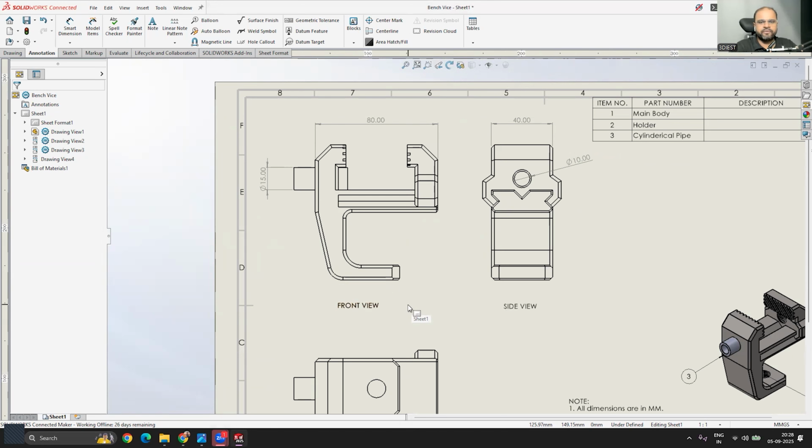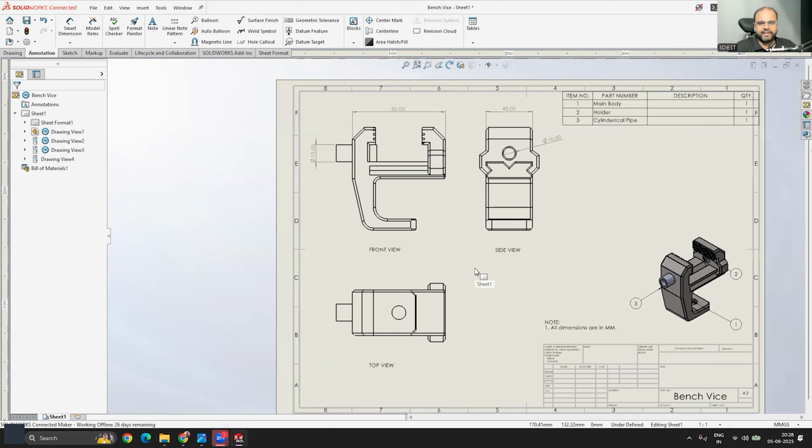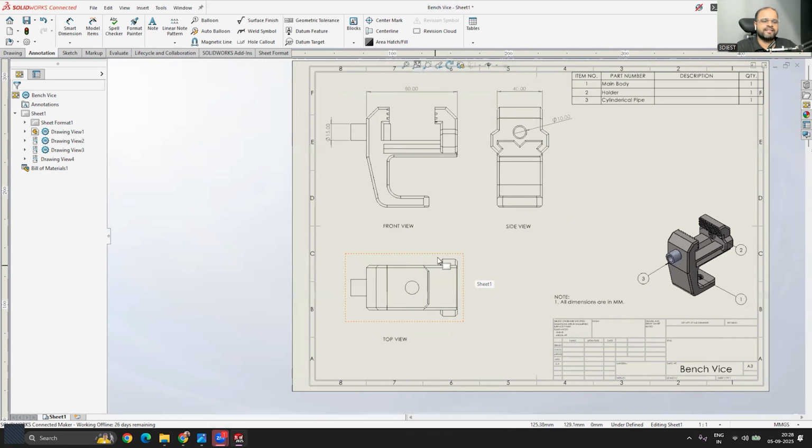If you have the spoon, and you want to get it made for real, in that case you have to share the step file with the vendor, not the 2D drawings, because creating 2D drawings is not very possible in the case of surfacing objects. So they share the step file with the vendor, and using that step file, the vendor will be able to use CNC or whatever machine they have. But in the case of spoons or any curves or organic shapes, it's not possible to create drawings like this, because the curves are not really accurate. Most of the time they have random radiuses, random diameters. It depends upon the flow of the curve needed, right? In that case, it's not possible.